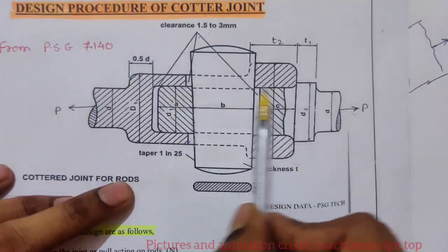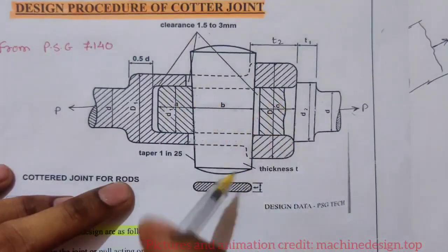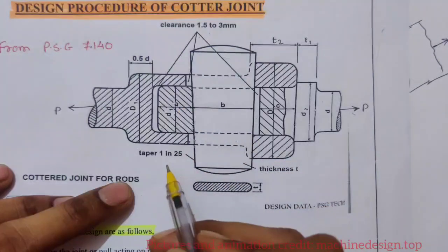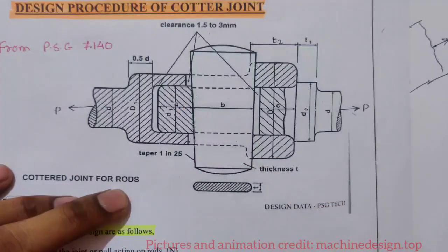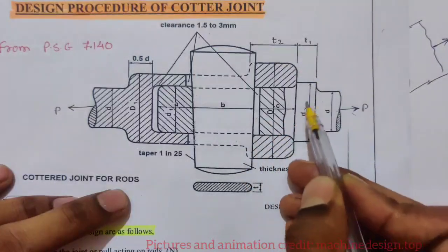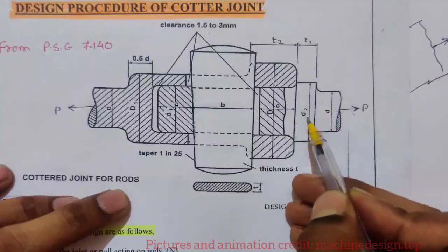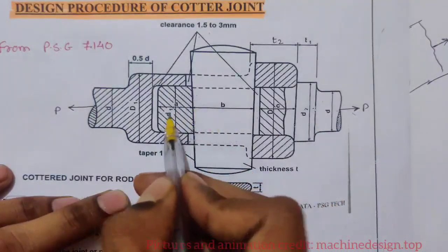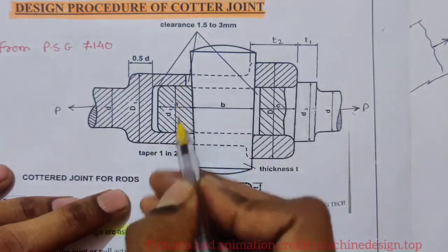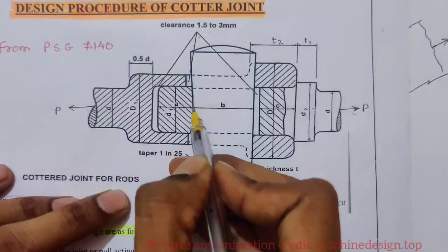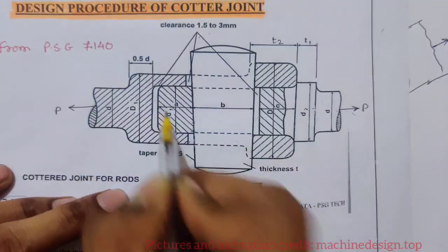Now how many dimensions over there in spigot? So this is one D1 and A and one more dimension, that is D2, but it is for spigot collar. So we should consider only 2 dimensions, D1 and A. D1 is diameter of the spigot and A is this thickness, this distance, end of slot to end of spigot.